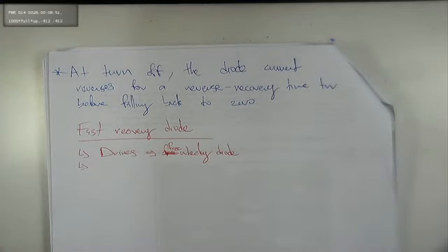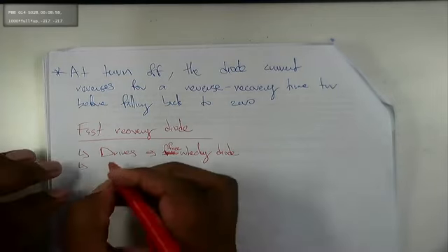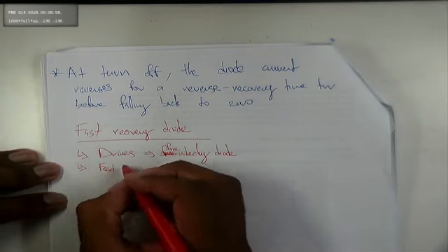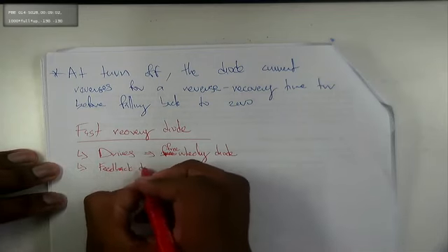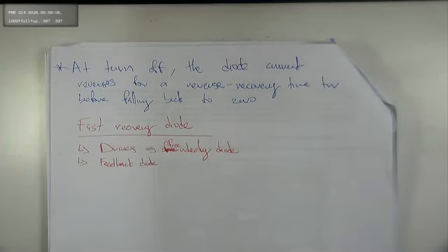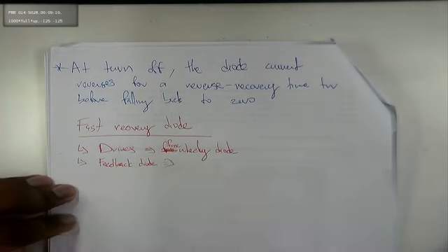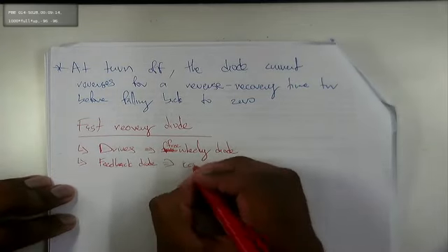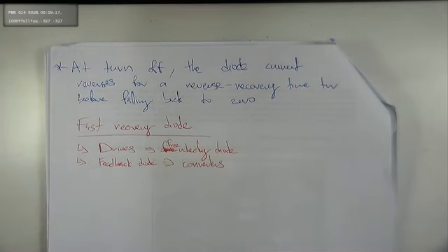This is used for inverters and converters, we can just say converters. So we have the power diode in general, then we have the fast recovery diode, with applications of freewheeling in drives and in inverters.